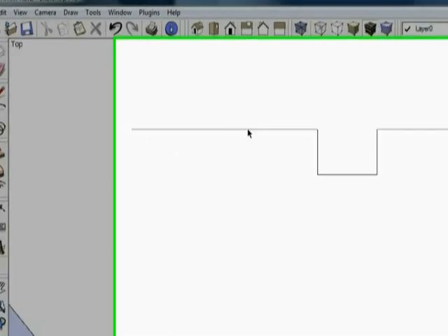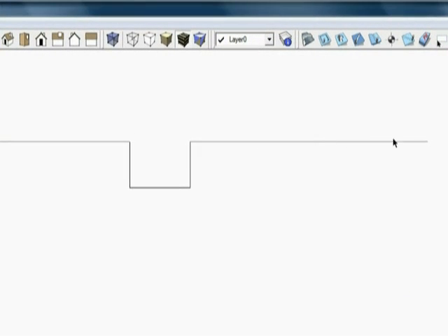Well, when it comes to a place where it's going to make a tab, that bit is going to stop, retract, however much, in this case 50% of the width of material, and then it's going to start again to complete cutting a portion of the material, and then it's going to stop, and it's going to re-enter the foam at the full 140%, and then it's going to continue on its merry way to complete the part. That's what the bit is doing in a standard tab configuration.